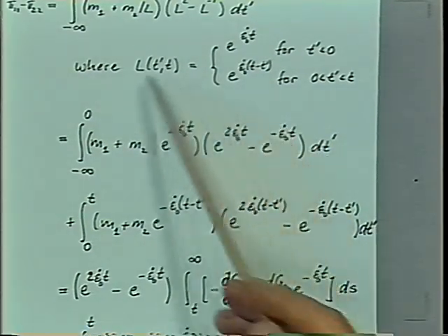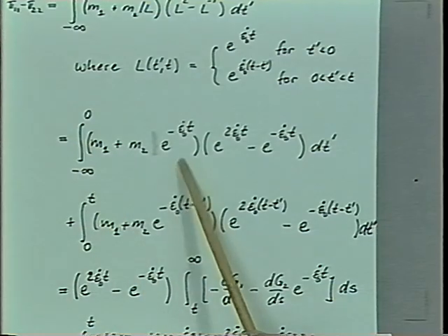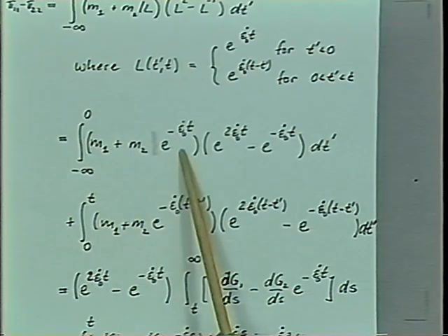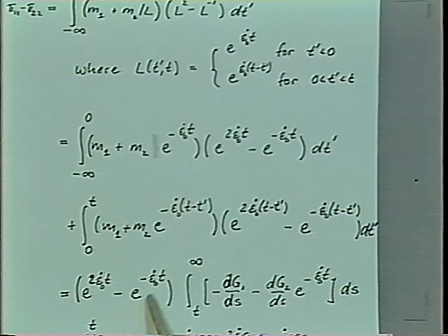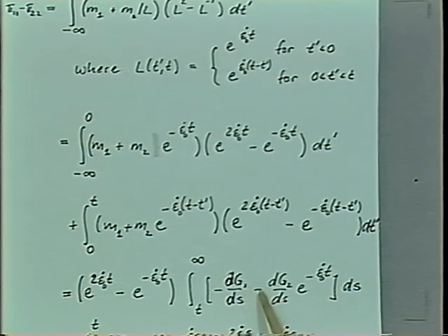All of this can be put outside since it's constant. And specifically, when looking at this part of the integral, this exponential function will also go outside. So the first part of the integral we can formulate very easily. We can replace the memory function with differentials of the relaxation modulus, the first part and the second part.